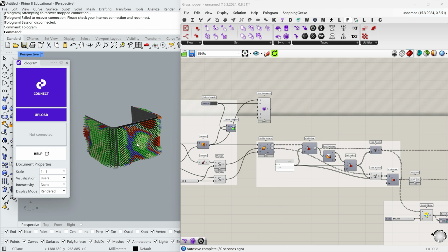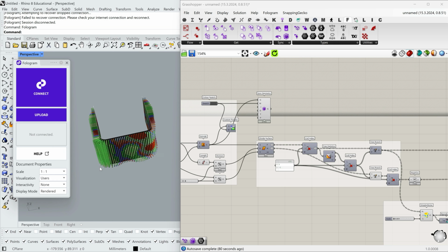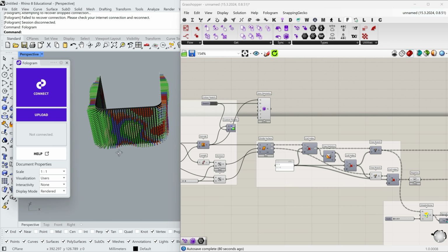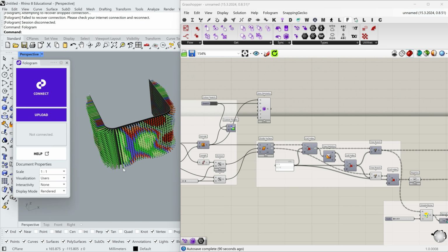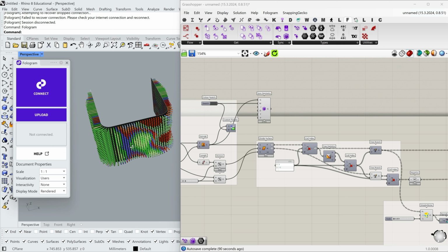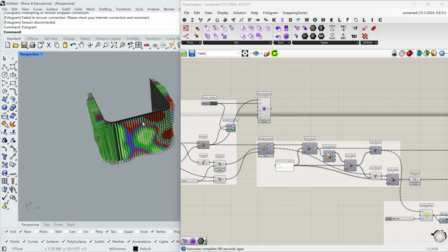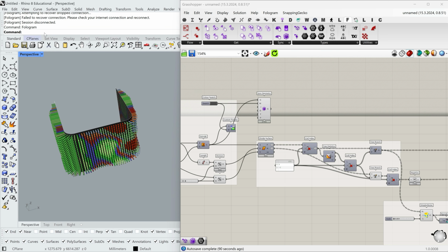But the good thing is, using Hologram, you'll be able to place it correctly because you can use XR markers. And let's place them right now. I'm typing in the command prompt XR marker, and I select the location of the mark.